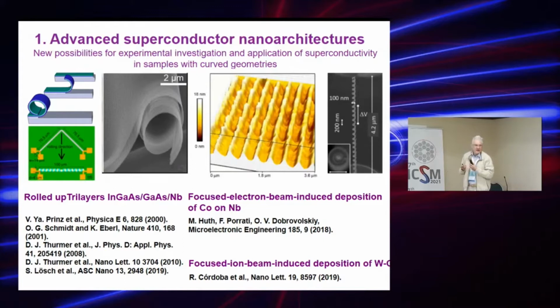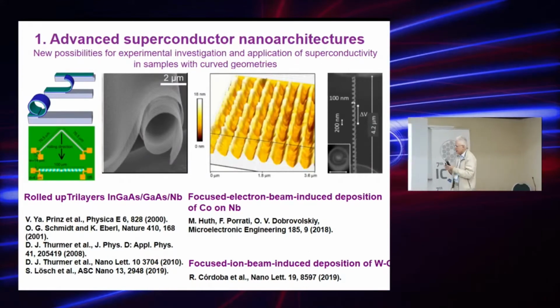the two layers which contact each other end up in a strained state. Different crystal lattices try to adjust themselves to each other, but this leads to the occurrence of strain. And this strain can be released by deformations. Deformations can be different, but under certain conditions which were revealed in the group of Viktor Yakovlevich Prinz, who unfortunately left us a few months ago, and Oliver Schmidt actively developed this field, the deformation is rolling up, as you can see.